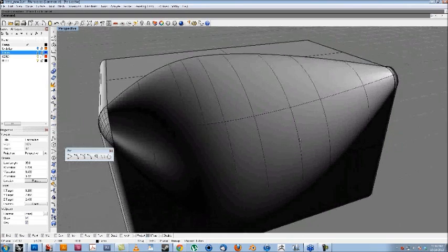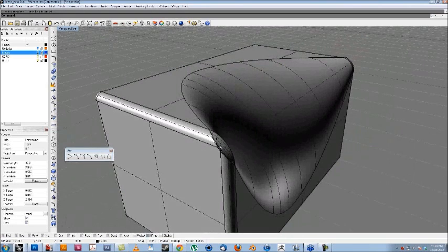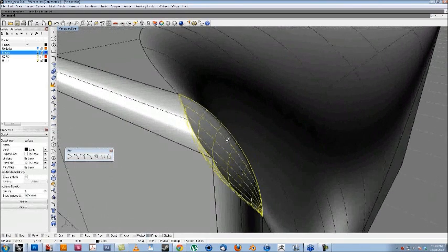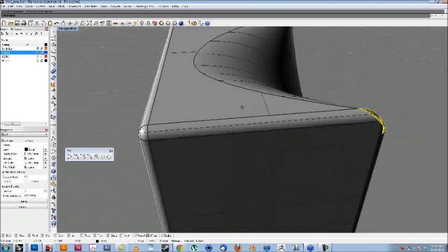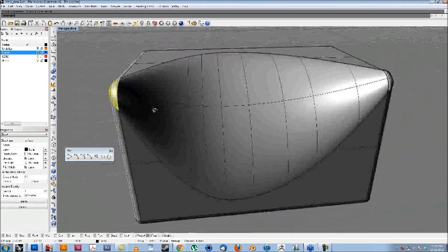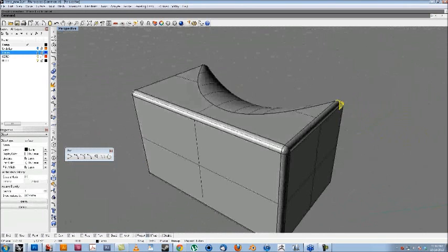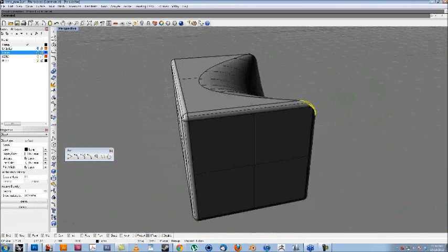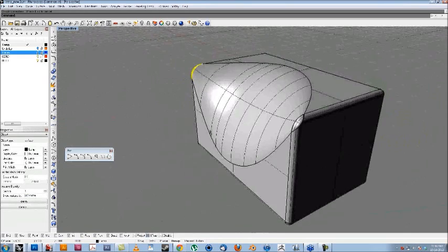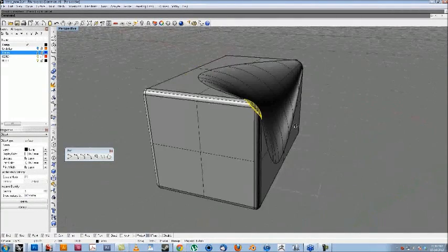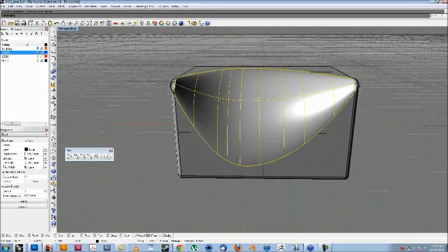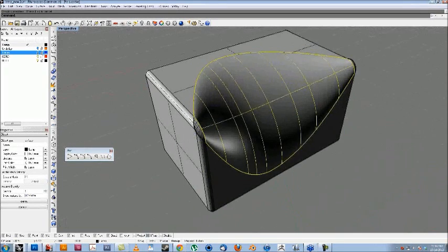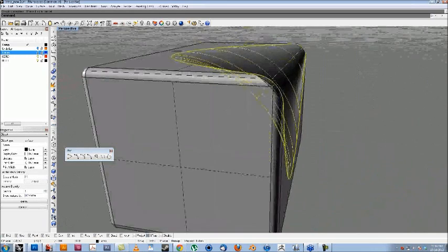I hate to dismiss the question with, just figure it out, but oftentimes that's all it is, experimenting with what fillets work. Rhino is great for surfacing, not the best for filleting, in my opinion. I think SolidWorks does a little bit better because it'll just not do a fillet if it won't work. Otherwise, I would say experimentation is definitely key.